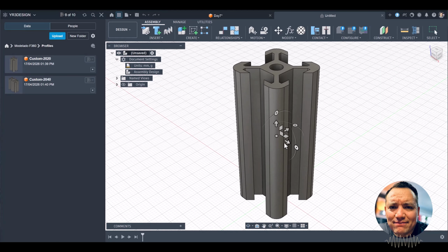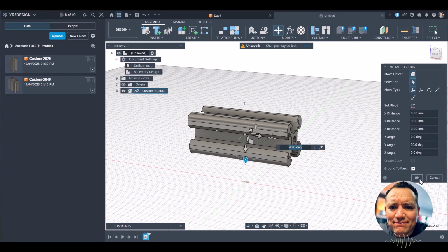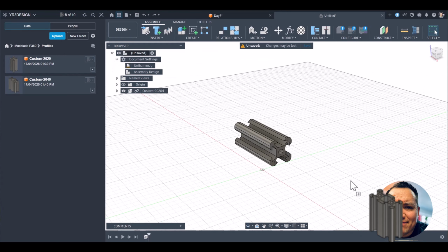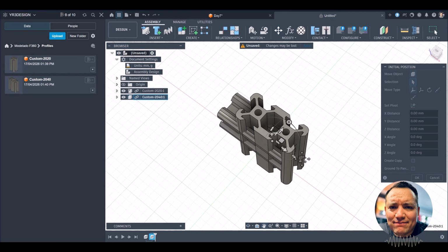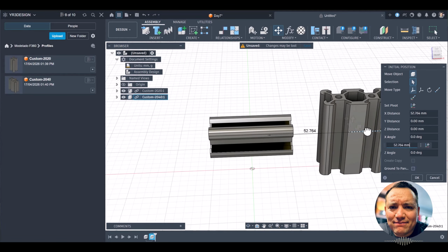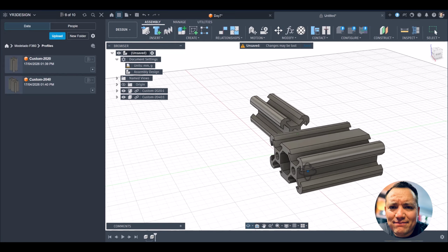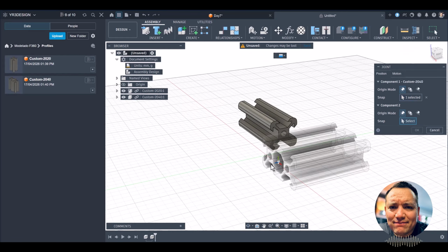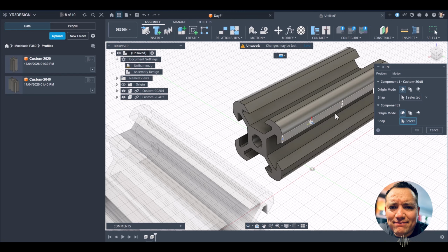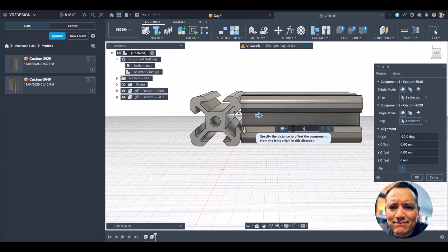Let's drag these parts. Let's drag the second part. I will place it in a different position. I will rotate it a bit. Okay. For a quick assembly, let's go to Relations, Joint, hover over the face, Control, click on this point. Now hover over the face, Control, this point. I'll move it a little bit, 6 millimeters, and hit OK.